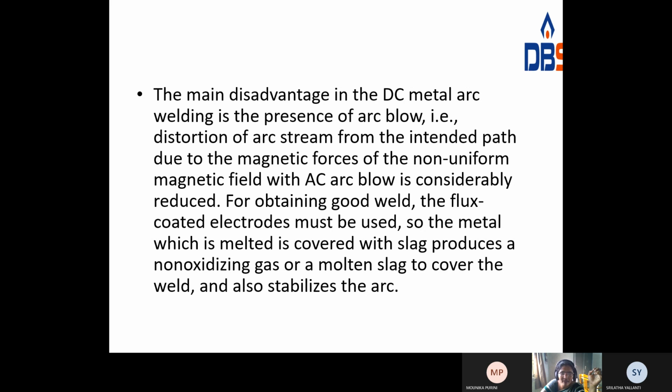For obtaining a good weld, flux coated electrodes must be used. To do good welding, we use flux coated electrodes. The metal which is melted is covered with slag. Why? Because it produces a non-oxidizing gas or molten slag to cover the weld. That means to stabilize the arc, you must use flux coated electrodes.